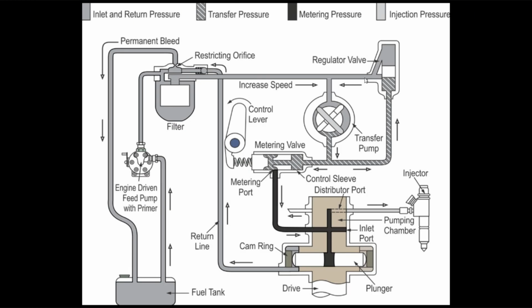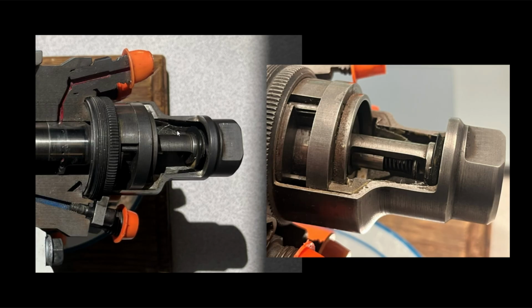After passing through the secondary filter, our fuel now begins its journey through the distributor pump, which is going to be this side of the diagram. Fuel flows in through the inlet by means of the vane type transfer pump, but not without passing through one final filtration element, the inlet screen. This final stage of filtration has holes as small as 2 to 3 thousandths of an inch, being the system's last line of defense. So, fuel comes in through the inlet, past the screen, and then the transfer pump, which is driven by the rotor of the injection pump, sucks fuel into the assembly.